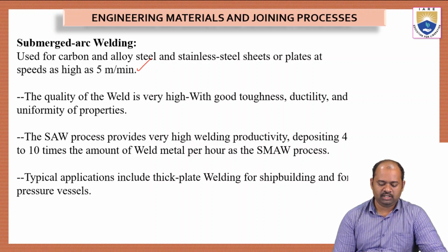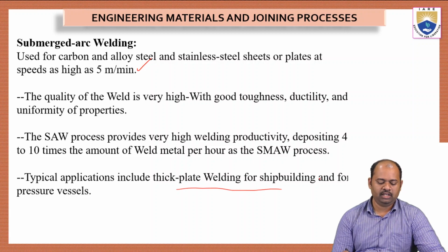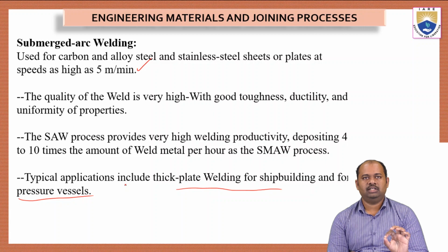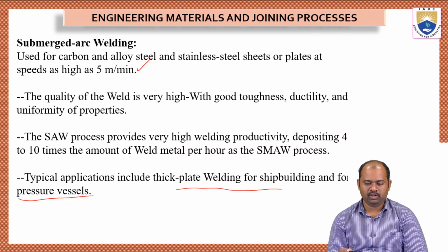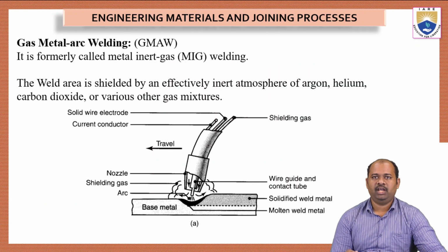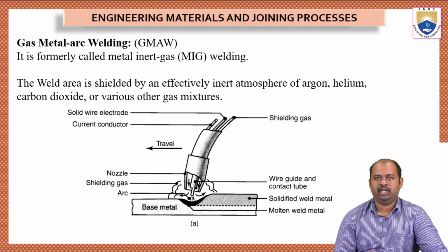And the typical applications include thick plate welding for shipbuilding and for pressure vessels. So in these applications, this submerged arc welding is very useful, and this process requires high skill and it requires more time. And then we have gas metal arc welding, GMAW.